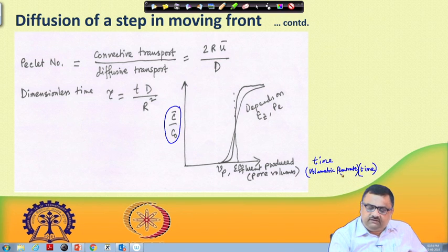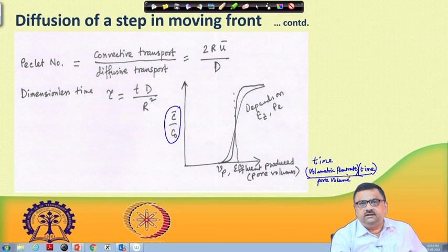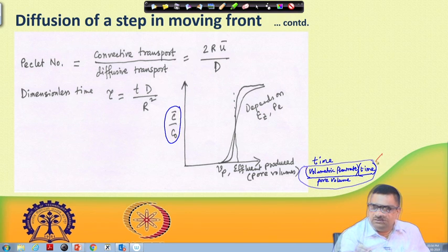And people have taken it further. Volumetric flow rate multiplied by time will give me the cumulative volume. So instead of that, you divide it by the pore volume, or void volume, for that particular medium. What this gives me now is the number of pore volumes.